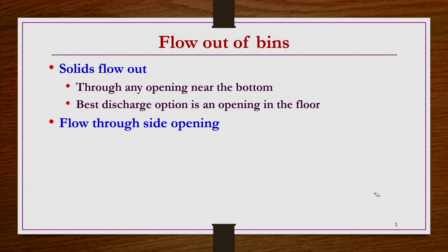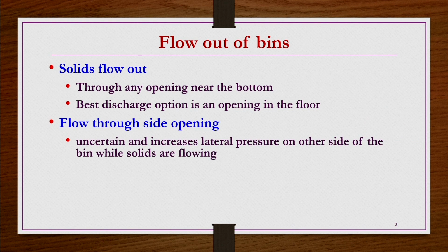right. Flow through a side opening is also possible, but it always gives an uncertain flow rate. You may not have certainty in the mass flow rate of the solids that you wanted to get, and that may also increase the lateral pressure on the other side of the bin while solids are flowing. Actually, once again we draw the same thing here.